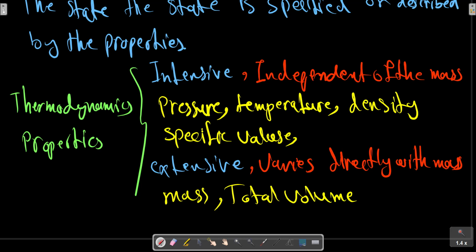In mechanical equilibrium, there is no tendency for the pressure at any point to change with time as long as the system is isolated from the surroundings. There will be variation in pressure with elevation because of the influence of gravitational forces, although under equilibrium conditions, there will be no tendency for the pressure at any location to change. However, in many thermodynamics problems, this variation in pressure with elevation is so small that it can be neglected.